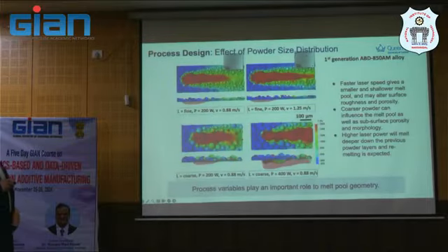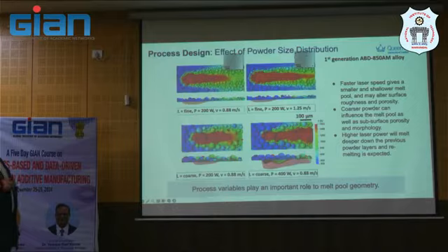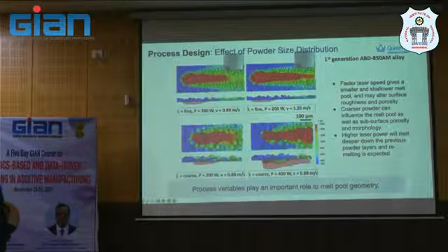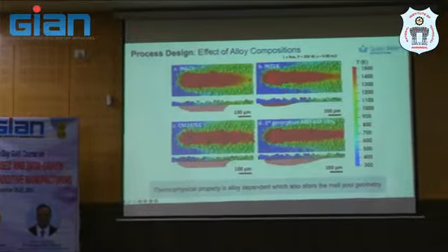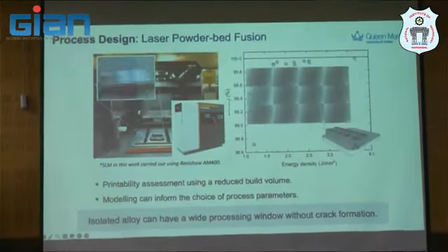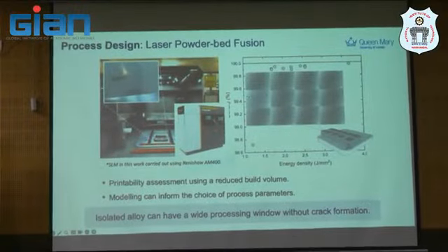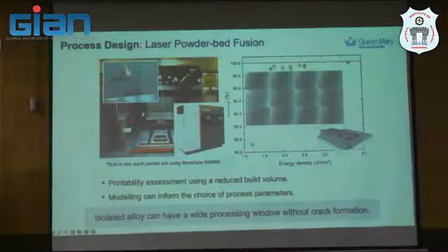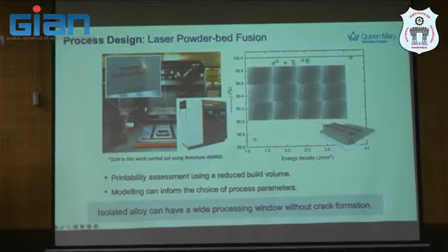And then we run a simple trial. At that time it's not very fancy, but it gives enough information for us to know the important parameters of processability for the new alloy we are going to develop, in terms of porosity that may lead to cracks, or surface morphology at different conditions compared with traditional alloy. And we then do the printing at a selected condition, using the ABD alloy series developed on the Renishaw AM400.